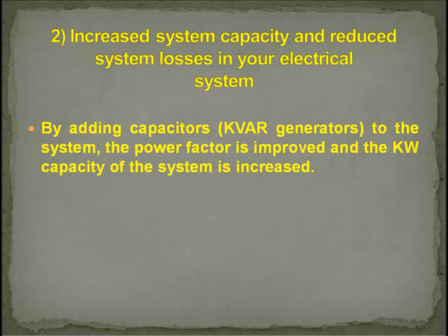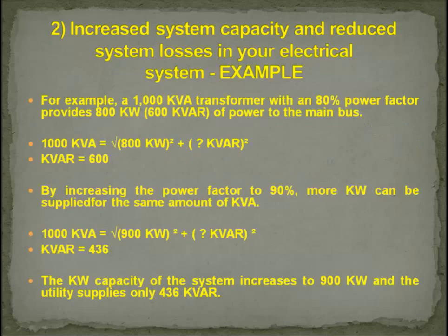2. Increased system capacity and reduced system losses in your electrical system. By adding capacitors, kVAR generators, to the system, the power factor is improved and the kW capacity of the system is increased.